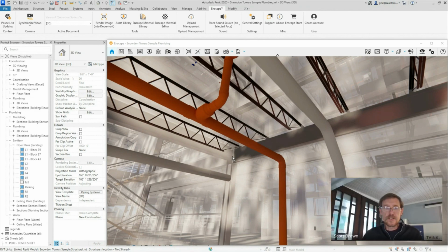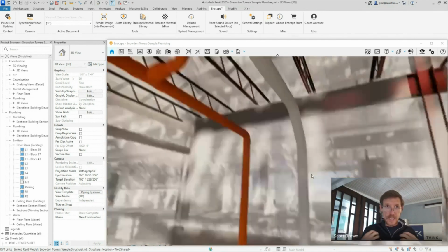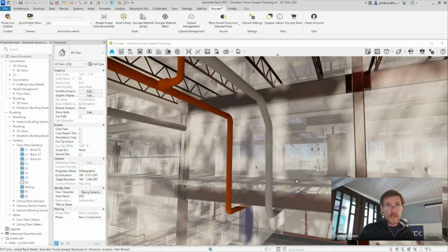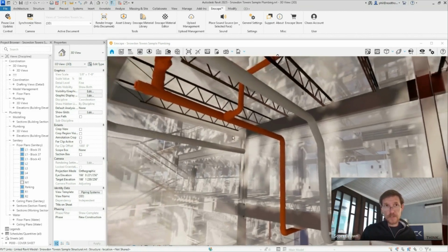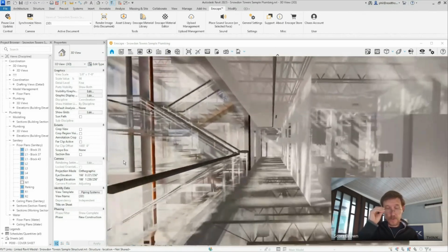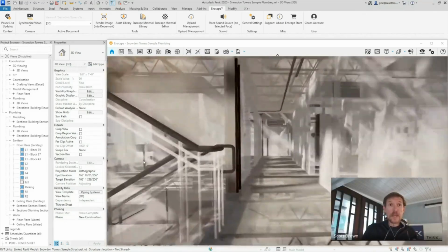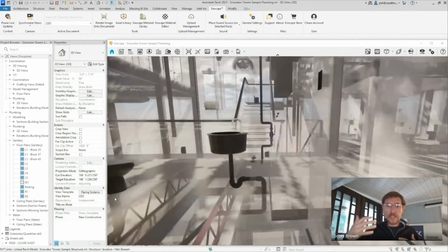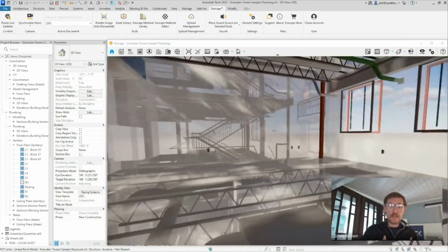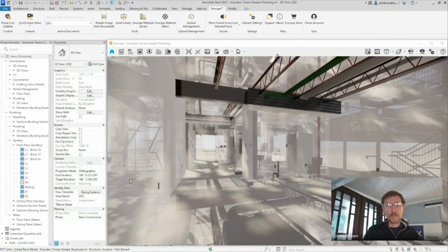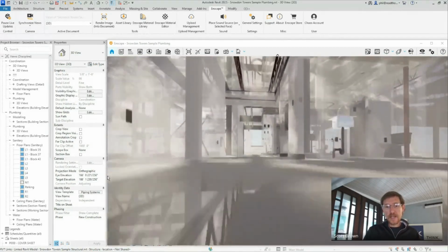Yeah, just so everyone's clear what he's talking about there. If I'm in my architecture model in Revit, I create a filter that says, oh, I want all my ductwork to be orange. I have a filter set up for that system, because that's your standard. Right. In Revit, I will see that orange, but for some reason right now, Enscape can't bring the filter of a linked model through to it. So what we've been doing instead is kind of